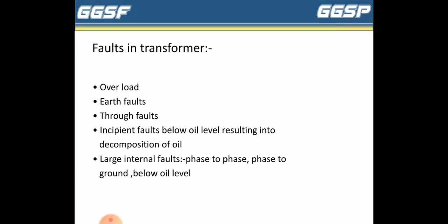Faults in transformer. There are so many faults such as overload, earth faults, through faults, insufficient oil, below oil level resulting into decomposition of oil, and large internal faults such as phase to phase, phase to ground, or below oil level.